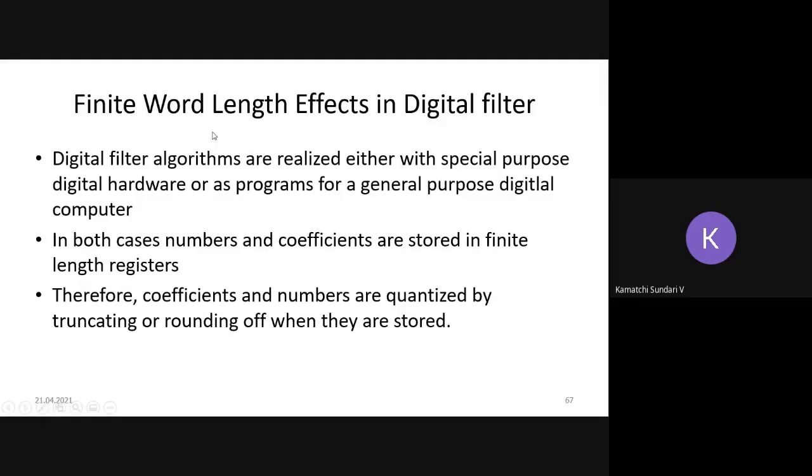And coming to the concept of finite word length effect in the digital filter. Normally the digital filter algorithms are realized either with special purpose digital hardware or as programs for a general purpose digital computer. In both cases, the numbers and the coefficients are stored in finite length registers.